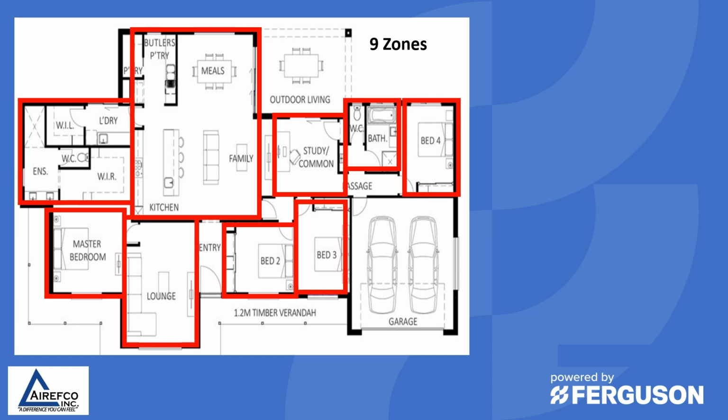Homeowners have the idea that a small bathroom can be conditioned by itself, along with small bedrooms that should not be zoned by themselves. But you always need to keep into consideration that if you do have a small zone, it has to be sized for the minimum airflow that the air handler or furnace can deliver.